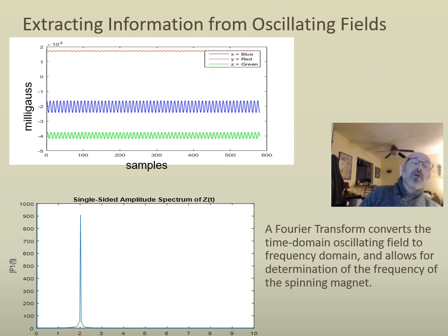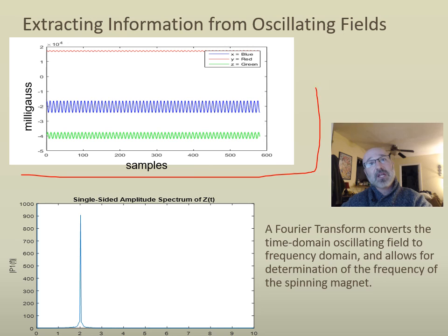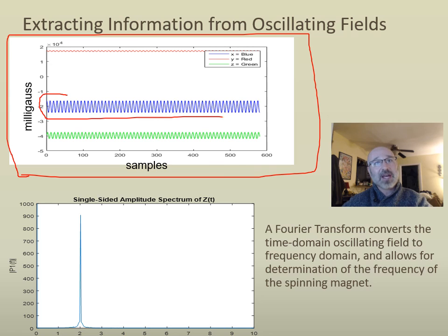So talking about our FFT and the need to go from our frequency domain and time domain back and forth between them, this up here in our top graph is the information that we get from our magnetometer. So we see a rotating magnet. This is what our magnetometer picks up. Now it has an X, Y, and a Z, depending on the orientation where we set down our receiver. So there's some averaging done within there depending on which axis we're looking at here. In this case here, we're looking at our x-axis here, and we can see we have this function right here oscillating in our time domain.